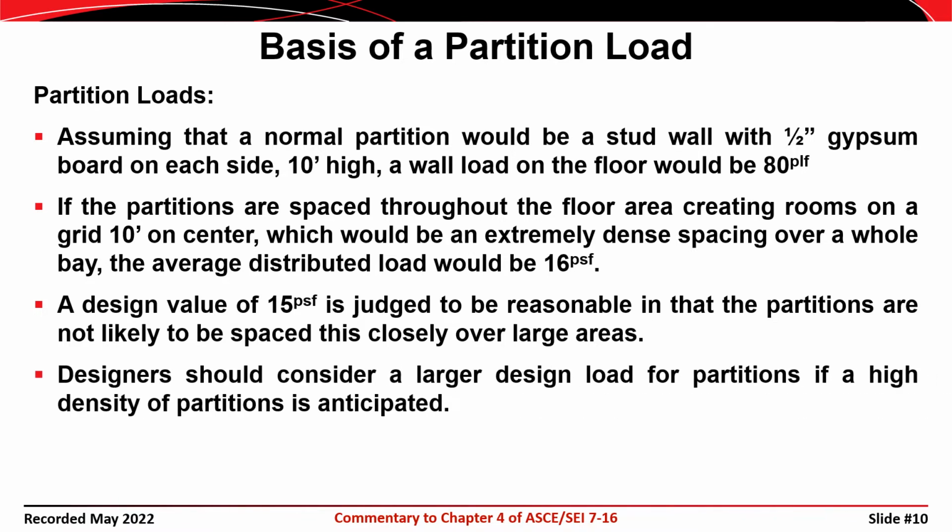But if you have different types of walls, you would want to make sure you consider that in your design as well. Maybe if you have a CMU wall or concrete block wall, that would probably give you a higher partition load than the 15 pounds per square foot.